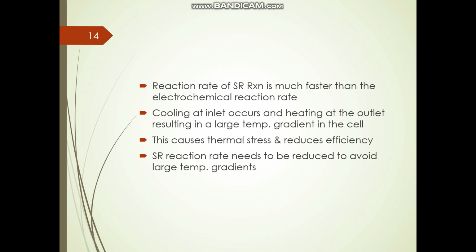Steam reforming reaction is kinetically more favorable than electrochemical reaction. Also, as we discussed, it acts as a sink due to its endothermic process. Hence, a temperature gradient is developed in the fuel cell, which further causes thermal stress and reduces the efficiency of the fuel cell.